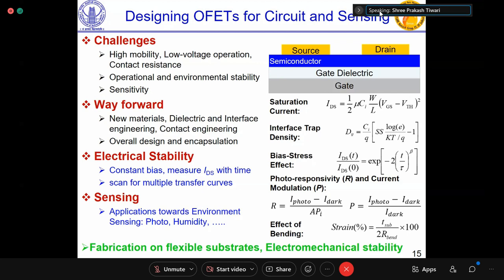In silicon, we rarely talk about contact resistance. But here, since source and drain are directly deposited metal, any metal may pose a contact resistance or Schottky barrier with the semiconductor. You can call it a metal-semiconductor Schottky contact. That contact barrier can result in something called contact resistance.